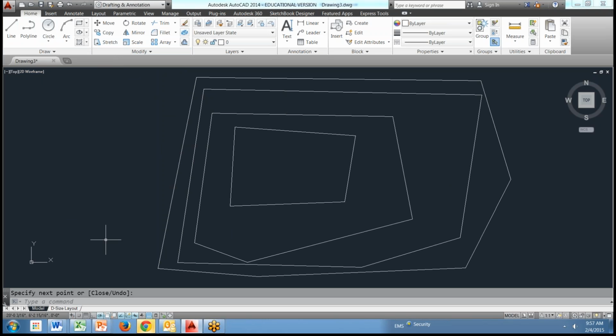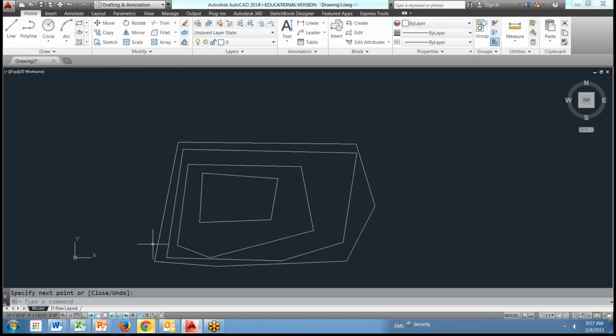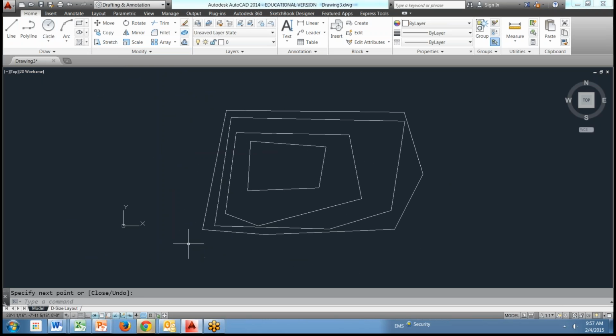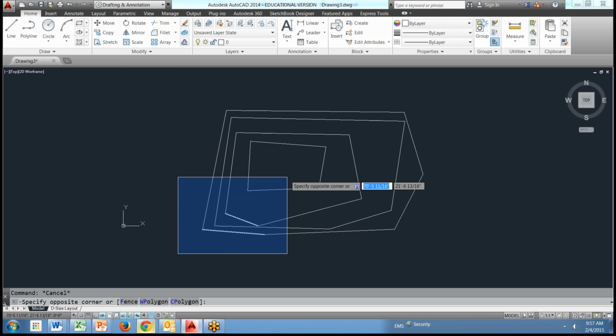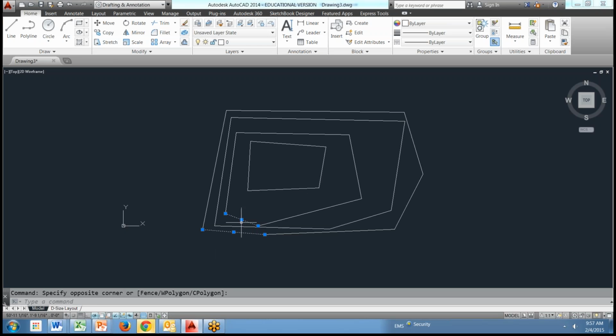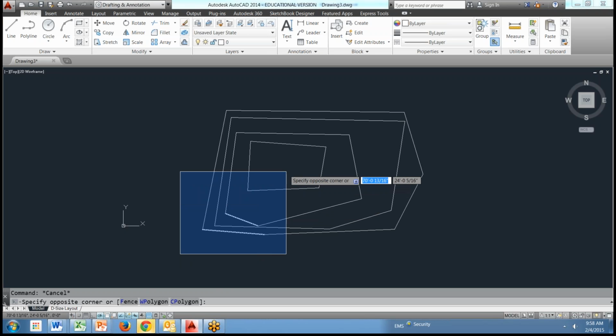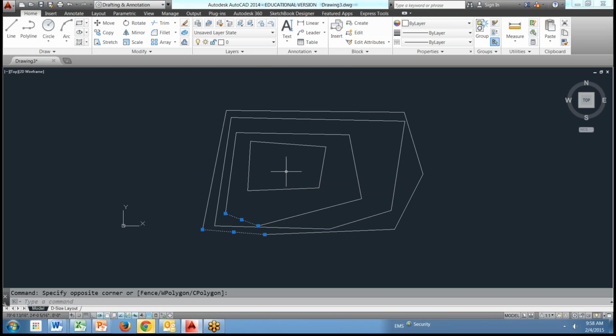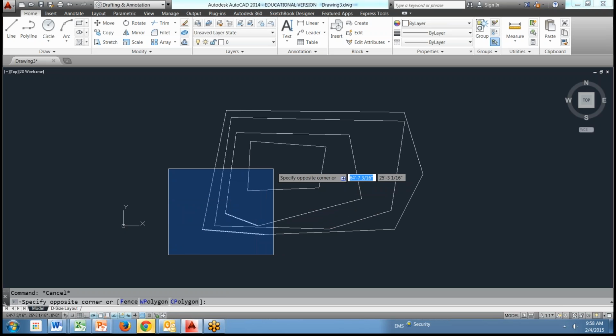This is another thing to talk about: your drag or your select. I can select a line just by hovering over it and clicking. Or I can make a box, which I basically click, pull, and click again. Notice that it only grabbed those two lines. Inside the box, only two lines are highlighted. That's the only lines it's going to do when I go from left to right.